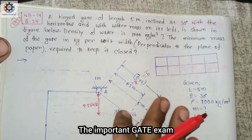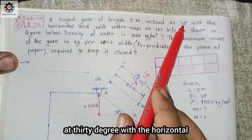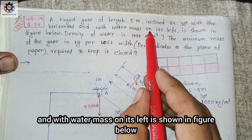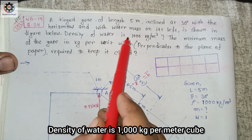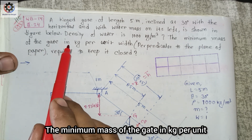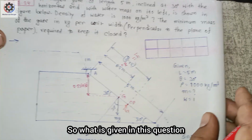Now we'll understand one important question that is very important for the GATE exam. Let's try to understand this. A hinged gate of length 5 meter, inclined at 30 degree with the horizontal and with water mass on its left, is shown in the figure below. The figure is given in this question. The density of water is 1000 kg per meter cube. The minimum mass of the gate, in kg per unit width perpendicular to the plane of paper, required to keep it closed. So what is given in this question?